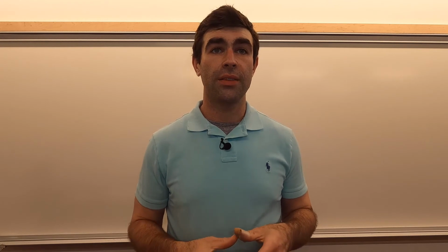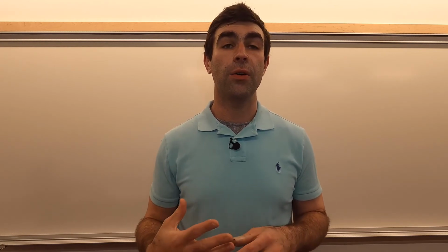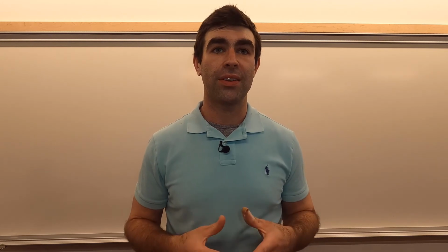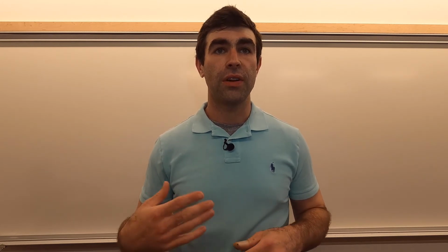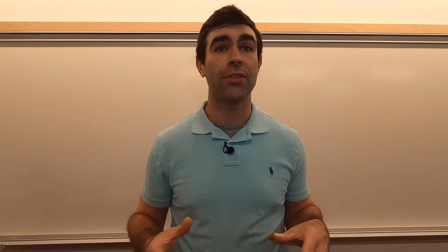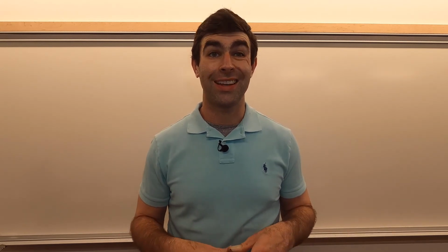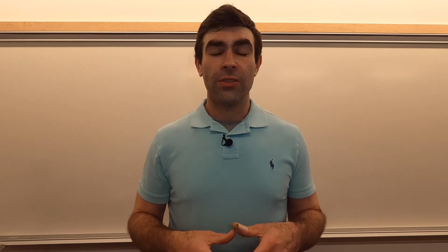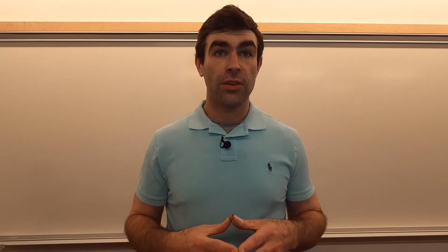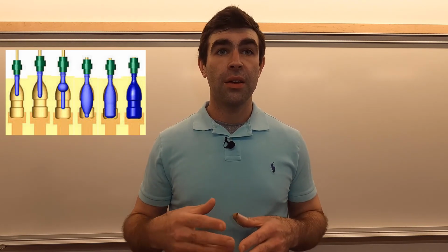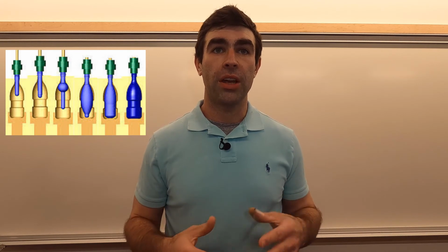Blow molding is a process that makes hollow, thin, or medium-walled thermoplastic products. Very high production rates are possible. Some companies make 60,000 bottles in an hour with this process. The process starts with something called a parison, which is just a little tube of softened plastic in the general shape of the object you want to make.